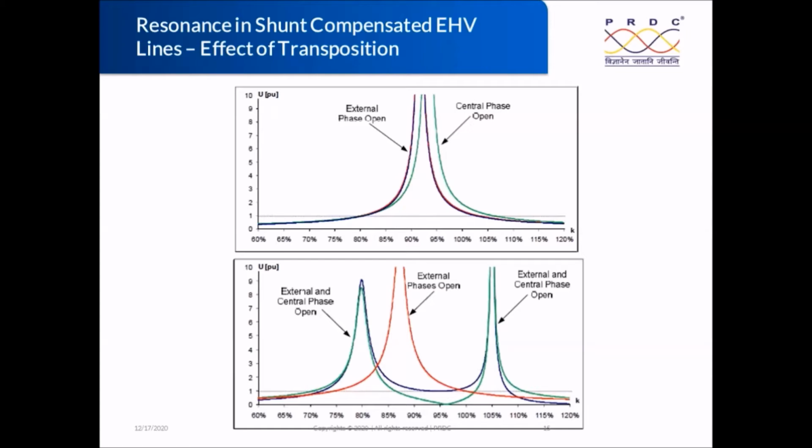The next, magnetic saturation of the reactor core. So where we are using the shunt reactors or line reactors, this also will be high, because this is going to change the inductance value, right? Once the reactor gets saturated, that inductance value is going to change. And whatever we have seen, that inductor is also participating in that network, so that is going to change. Basically, once saturation occurs for the reactor, the inductance value will come down. So this is going to reduce the amplitude of the overvoltage magnitude. If it is not saturated, it may generate very high values.